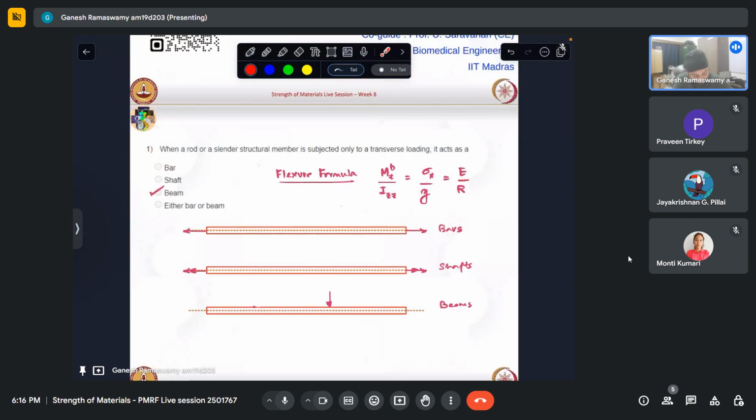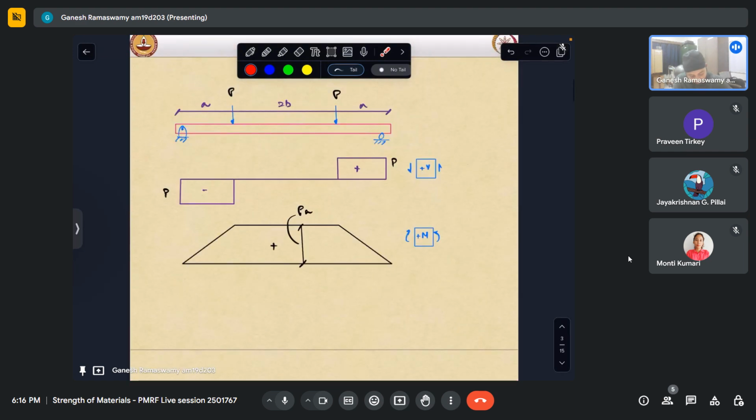So our flexure formula, which we apply throughout this course, is actually valid only when the bent curve is part of a circle with a constant radius of curvature. This gets violated when we go into sections where there is non-zero shear force. In sections with non-zero shear, the arc will no longer be a circle but a higher degree curve.